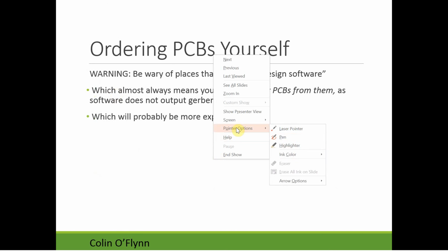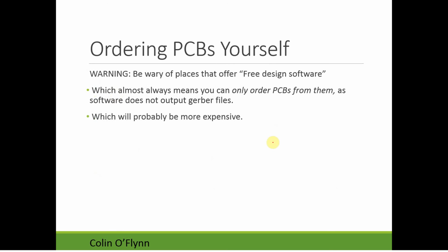As a warning, there are a few companies that offer free design software. They say, oh, download our free software, so you don't need to learn Eagle, and order boards through us. Their software can almost never export the standard Gerber file format, so they lock you into ordering boards from their website, and their boards are a lot more expensive than any other option. I know it's happened before where students have done the design, and then Mark had to order them, and it's like $200 for these 2 circuit boards that would have been 20 bucks or something. So it's a lot nicer to use generic software like Eagle or another one, as long as it can output these Gerber files. That's the real key thing to always double check, is that it can output that, and then you can order the boards from anywhere.